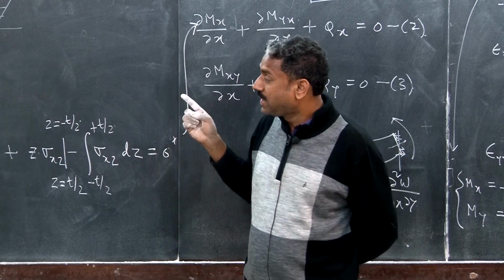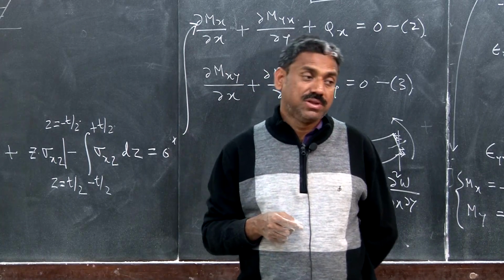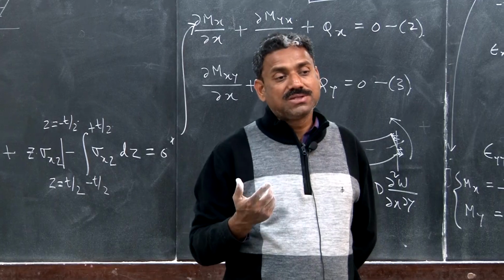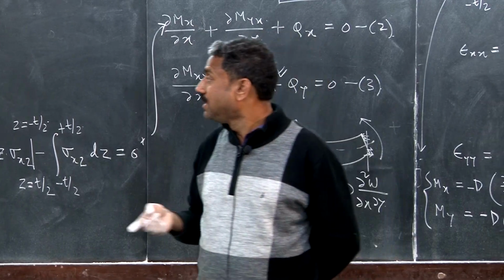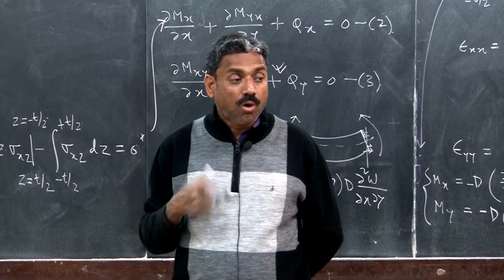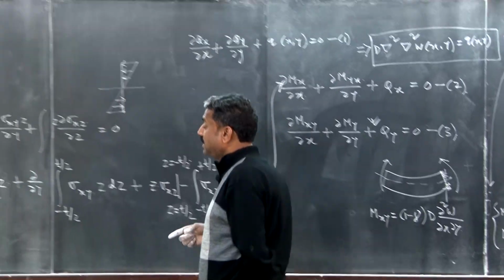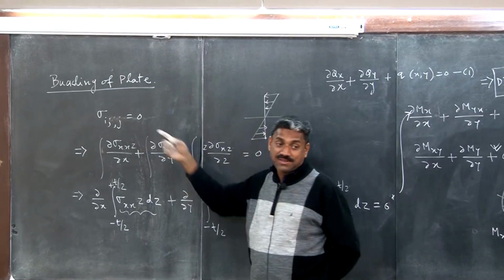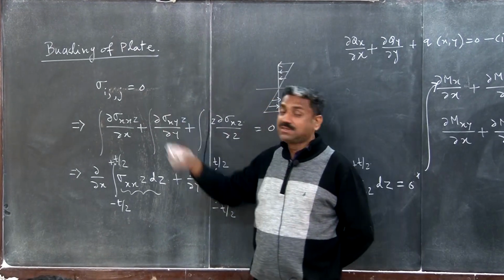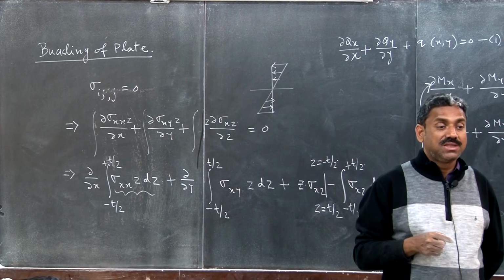Once again, when we write down the equations in the deformed configuration, some additional components of stresses will come. That we will see. Once again, that can also be done directly by considering the force resultants in unit width, or you have to consider the stresses, the equilibrium equation, but not this. Now this is the Cauchy stress tensor equilibrium equation, which is basically in the deformed configuration.